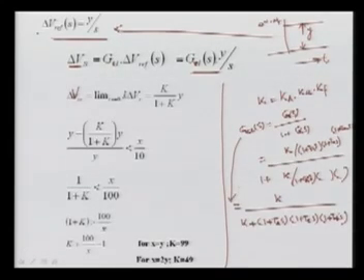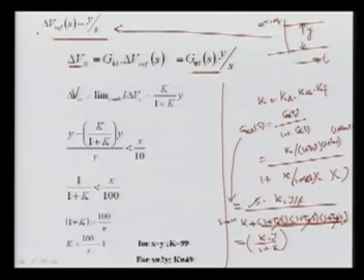Now what we are doing, we are just multiplying here. So this complete value we are going to write here into Y upon s into s, and s tends to 0. So what happens, this is cancelled out, and all these, if you put s as 0, this is 0, this is 0, this is 0, and finally what we are getting is plus 1. So we are getting K Y into 1 plus K. Here it is unity, this value completely. So we are getting this, and you can remember here, this K upon 1 plus K into your Y value.